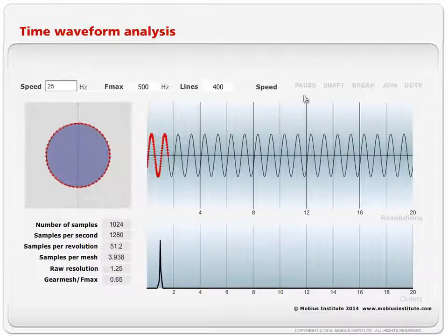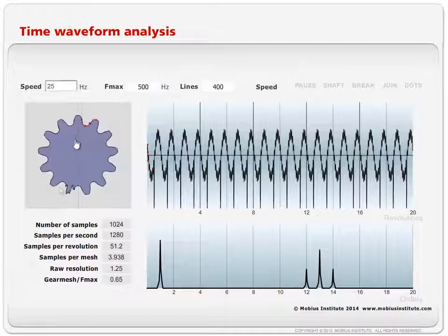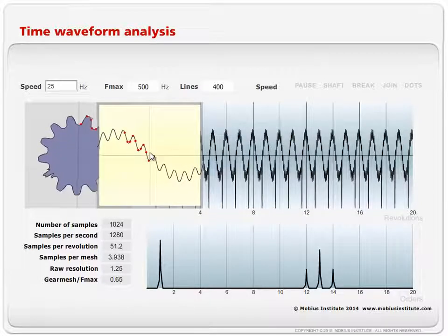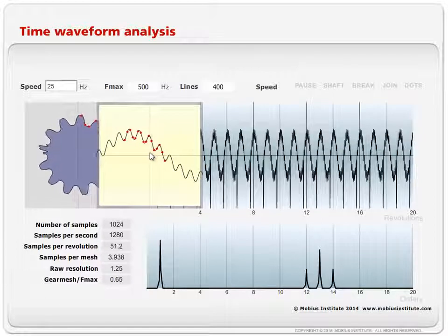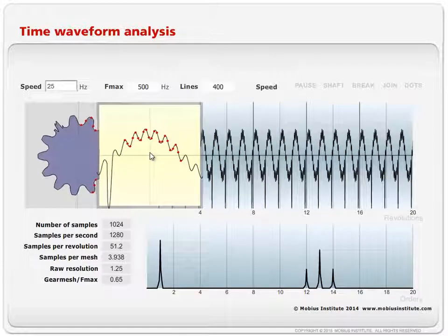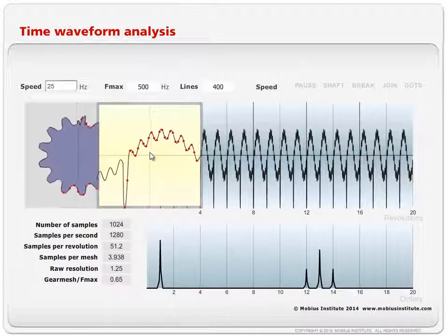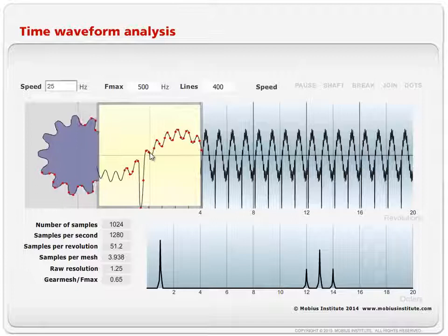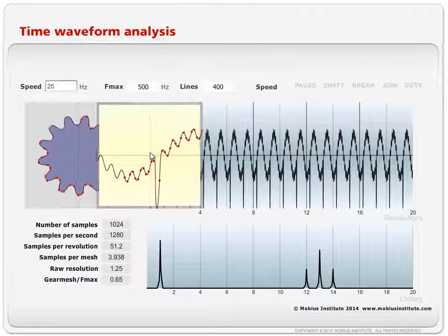So that's all very simple, but what if it was a gearbox, or gear, and there was damage on it? Well, we can translate these little red dots onto the surface of the machine we're testing, because just as the camera takes a whole bunch of shots, it's also like taking little mini pictures of the gear as it's going past. Now, if you watch on the left, you can see the damaged tooth, and on the yellow graph you can see that there's only maybe one or two red dots on that spike of vibration.